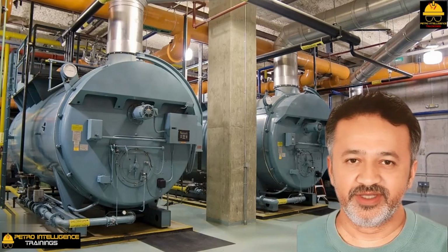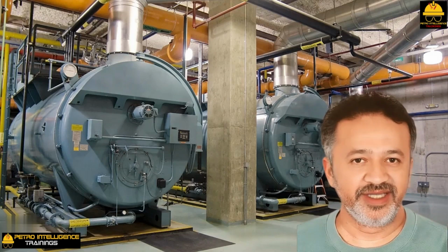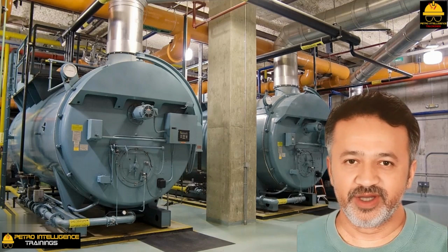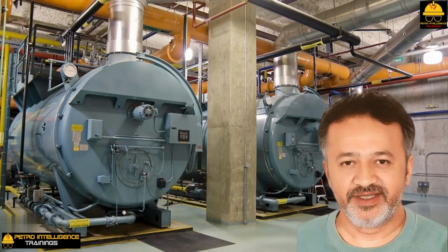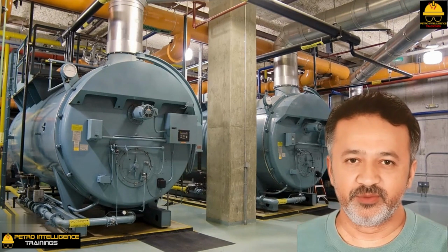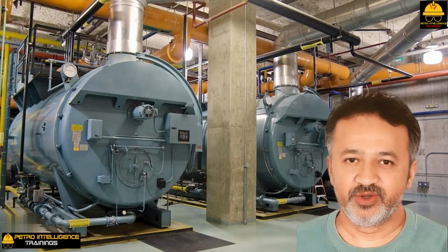An important feature of steam generation in a process plant is steam condensate recovery. This is usually a function of proper design of the steam condensate controls on individual steam heaters and reboilers, as well as proper design of the condensate recovery system. Experience shows a reasonably good condensate recovery rate in a large, complex refinery is 70%. A substantial portion of the steam is used for process steam stripping, purging vessels, instrument connections, flare dispersal, and other non-recoverable uses. Thus, the 70% rate is really rather good.